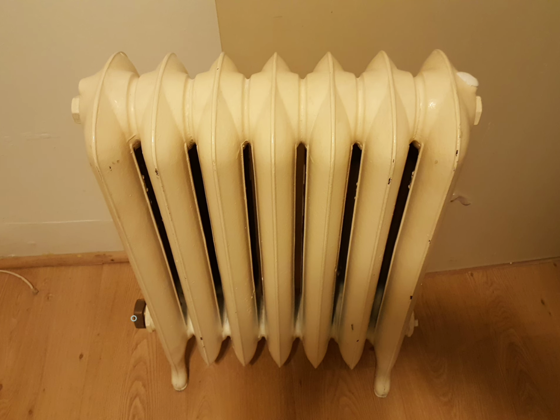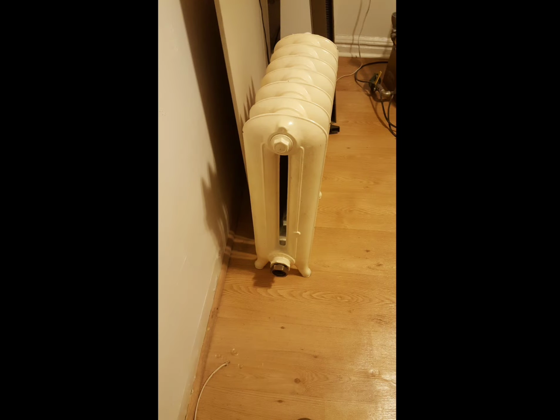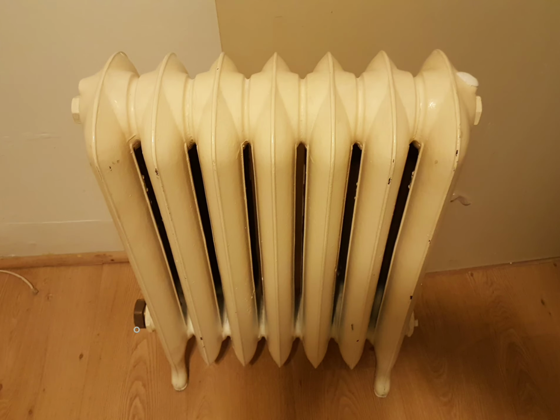The valve is not there because it's been removed, but there would normally be a valve in its place. So the way it would work is the steam would come into the radiator through the service valve, make its way up the first section, and start slowly making its way to the back sections, working its way from the top and then all the way back down to the bottom. I don't think I have an image of this particular radiator. I should have taken more pictures of it. However, I don't have it. But there is an opening here for an air vent at the lower portion of the radiator.